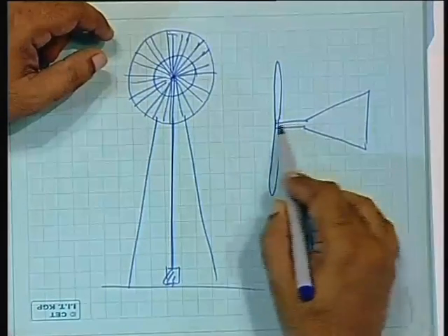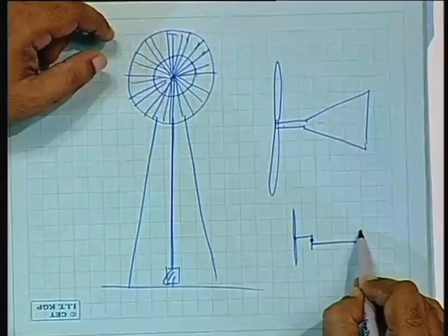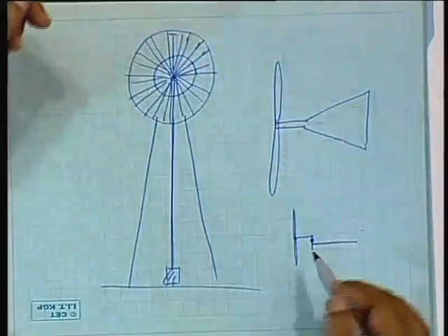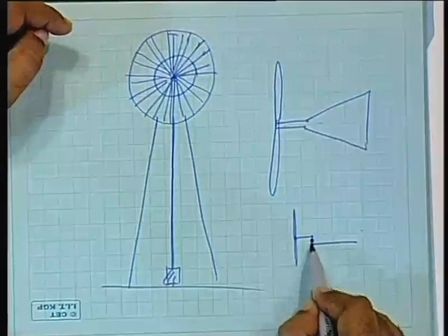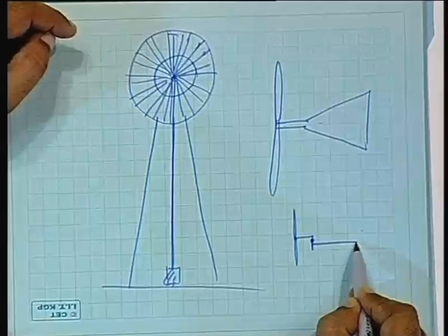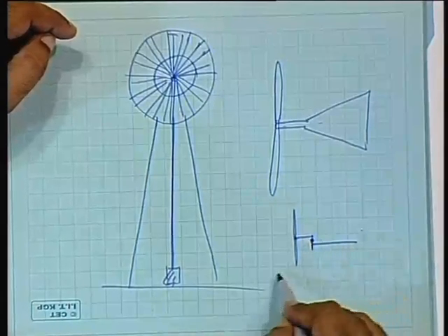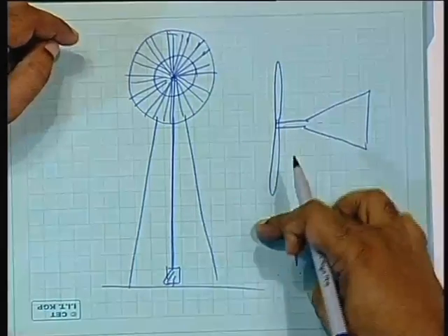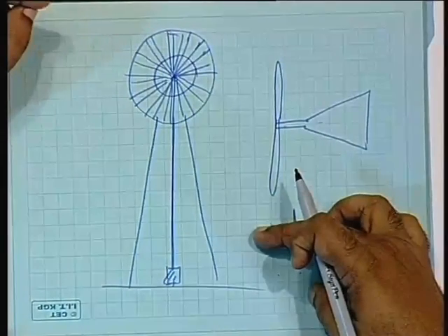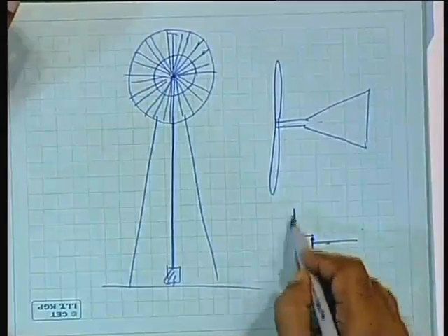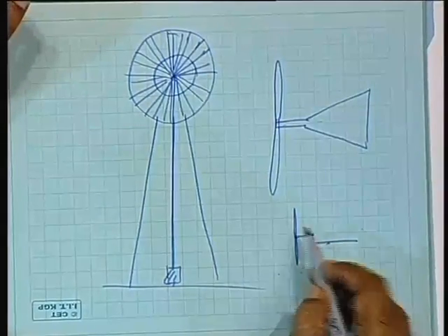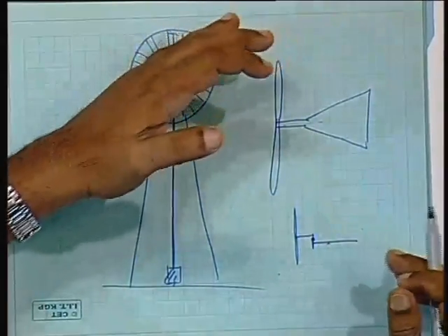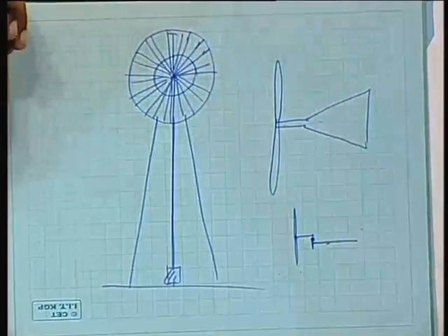Earlier you'd think that this is in the same direction, right? If you look from the plan view, then it is not really in the same direction, slightly off. As a result, when the wind speed is less, then the force on this one dominates, and it orients it along the direction of the wind. But when the winds are large, then the thrust on the blade will dominate, and it will disorient it away from the direction of the wind.